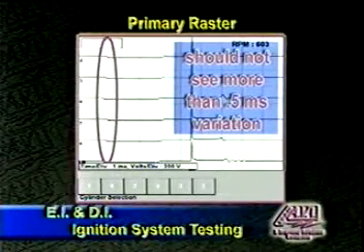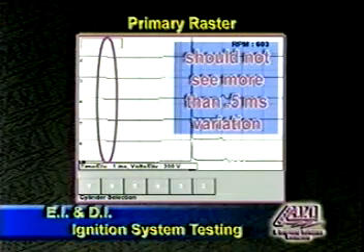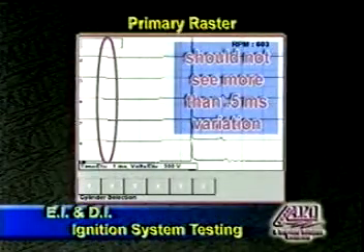So a maximum of 500 microseconds, or 1/2 of 1 millisecond, variation is perfectly normal. When you have mechanical slop or a magnetized distributor shaft or shutter blades, you will see an abrupt, massive misalignment of the point of primary turn-on on this raster pattern, indicating a primary dwell variation problem.